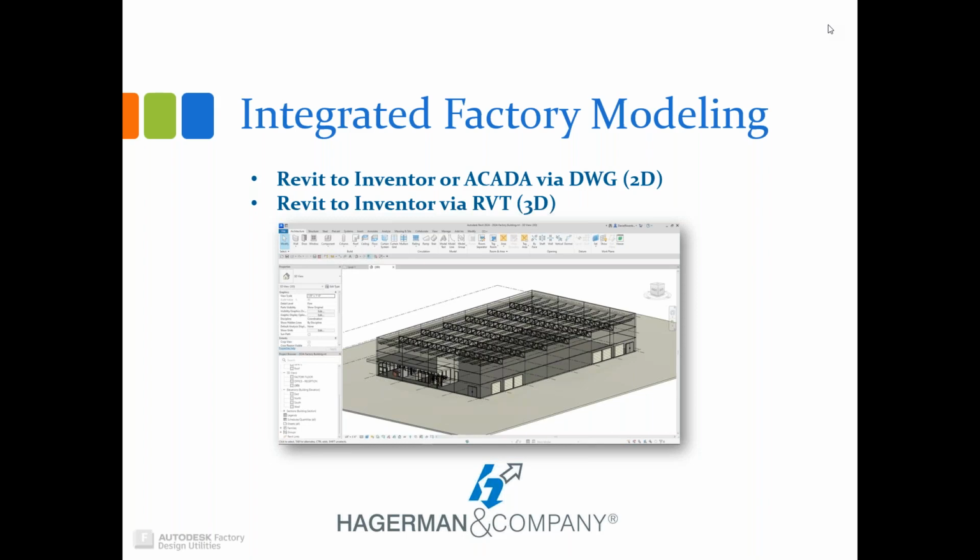Now, if they're using Inventor and they want to see your model linked into theirs in 3D, you can basically just send them a copy of your Revit model. And that's what I've done with Mark. The default file type for that is just an RVT. So you'd basically just be sharing your working Revit model. It doesn't really require any cleanup or anything.